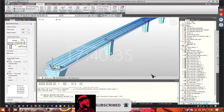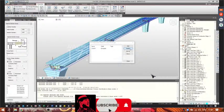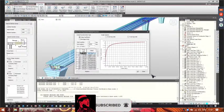Going in the creep-shrinkage menu, we have already defined one law for our concrete 37. And we choose the code we want to refer to. In our case, we choose European, and entering the FCK of the material and the humidity, or the notional size of the member, we have defined the relation, except for the age of beginning of shrinkage. Here, according to Eurocode 4 part 2, this age is 1 day. And now we can show results and check the function.